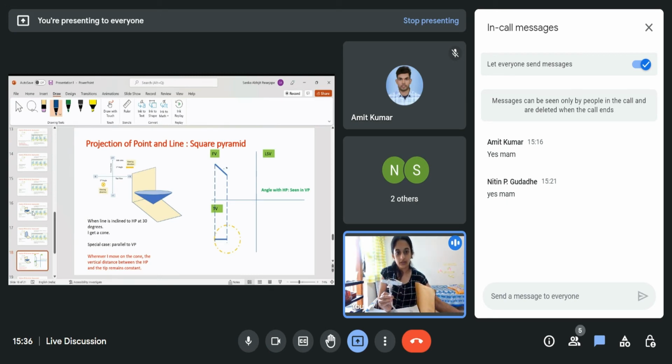So this is the projection. Okay. Right now in this position, this is how the projection will look. This is the true length of my thread. And what if I look at it from the top, I see the projected length, which is L cos 60. Okay. So this is L cos 60 for this case. Okay. Now let us see. I'll rotate. This thing has been going down for a little while. I'll just get it up.